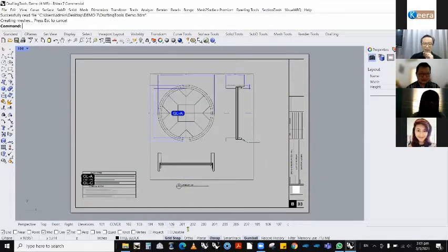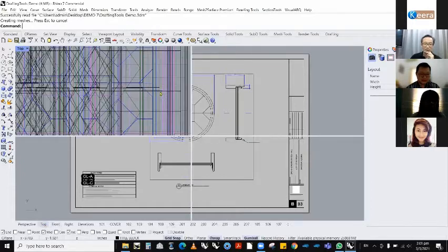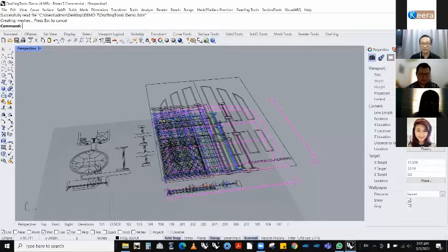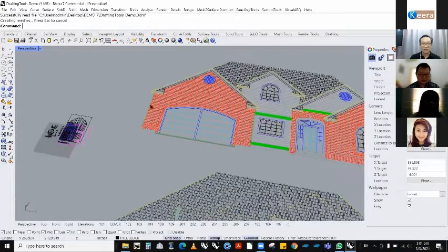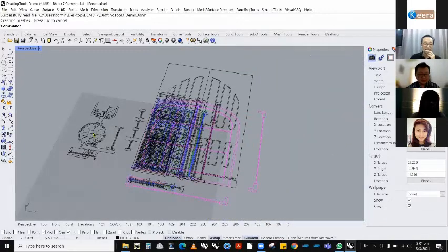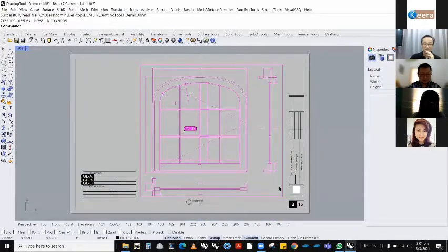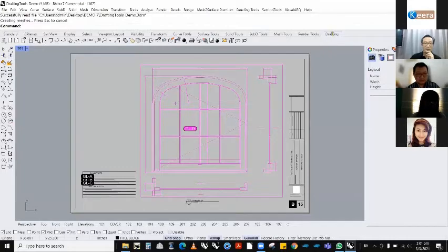I could add on. If I go back to my top view, this is all my Make2D drawing. This is all my section. I could probably put in different layers. This is the main space that I work in. Once I need an additional title block, I could say add new layout if I want. Otherwise, the drafting tool is found here, and these are the tools available for you on the drafting part of this.